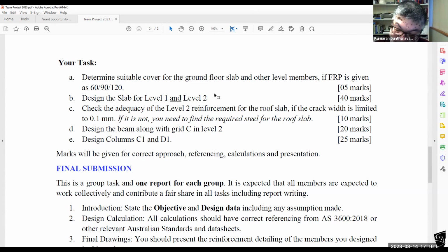Today we discuss the deemed-to-comply method for beams. Similarly, we have a separate equation for slabs. You have to use that one and see whether your assumed values satisfy that inequality. If yes, that is a win, you can proceed. If not, you should change the thickness and recalculate and recheck the deflection, and make sure you pass the deemed-to-comply deflection check.